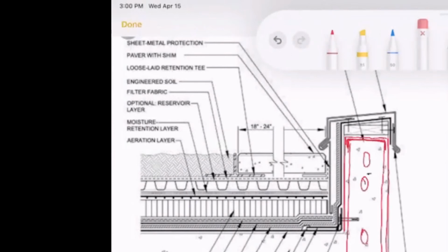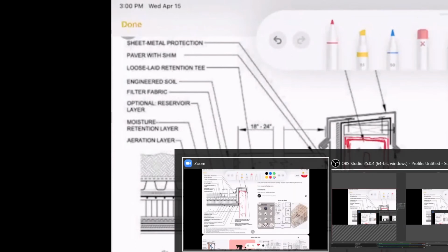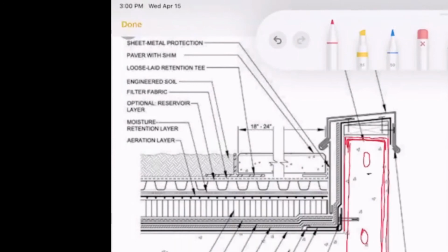It's spacing like that. And then I can go in here on the metal stud and do my sheeting, and the sheeting will stop right there. And that will be my dense glass. And then I can come here with whatever I want to finish. If it's a rain screen, like a metal panel, whatever I can buy, I can put those panels right there, assuming I'm doing the detail. And of course, this thing will be farther out right there.